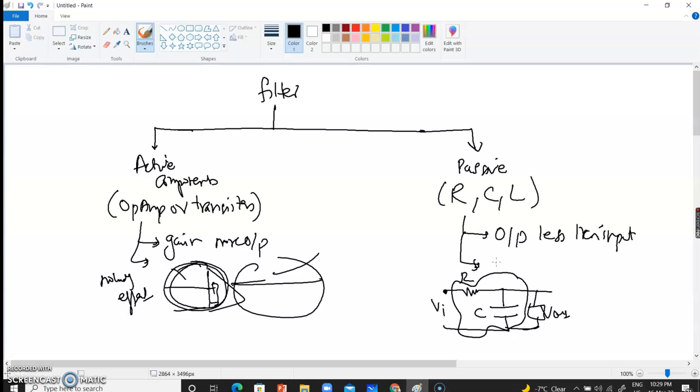Whereas for passive components, the circuit can get loaded and its values disturbed depending on the output resistance, right? Over here, it's totally isolated, so it doesn't really matter whatever output or whatever load you are going to connect on that side. So basically, active components are good, and if you design filters using active components, that will be more useful.